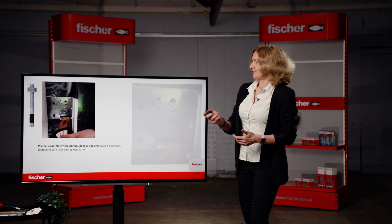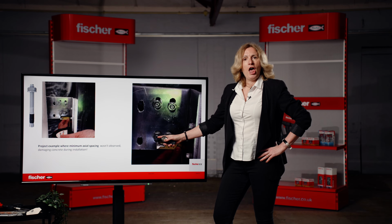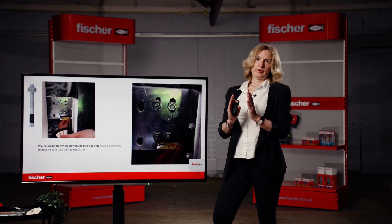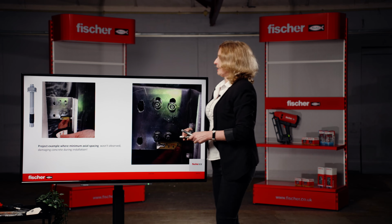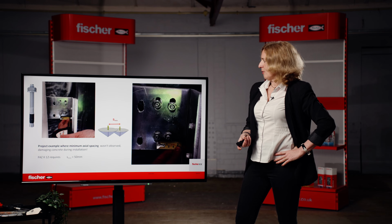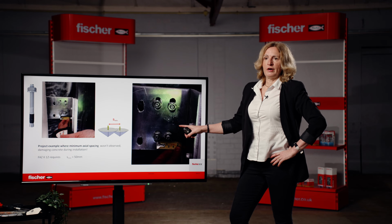assuming 4 fixings will be better than 2, yes? Unfortunately not. If you zoom in, you will see a very frightening example. M12 expansion anchor installed with only 25 millimeter axial spacing. What that means, those fixings installed so close together will damage the concrete between the expansion clips. If you look at the minimum allowable axial spacing for FAZ12, it's 50 millimeters. In this case, we had only 25.